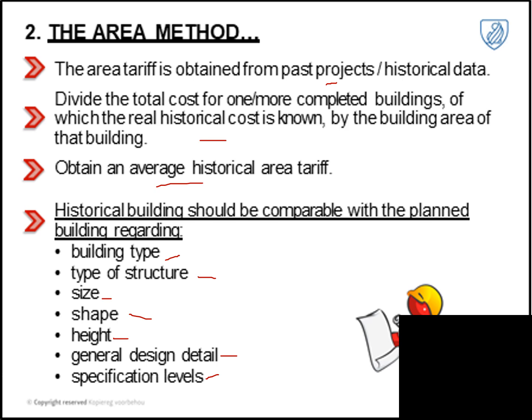So you need to make sure that you keep your estimate as accurate as possible. And always very important, once you've done your estimate, compare it again to other items, for instance the AECOM report or what you've seen in other projects. Don't just compare it to one project. Look at whether it makes sense or not. It's paramount that you do that in your estimation.